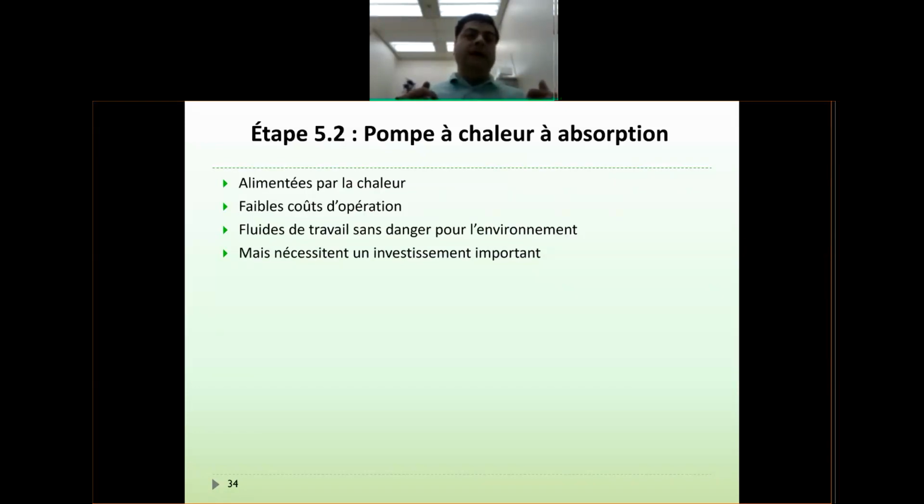So if you remember, when we discussed the six steps of process heat integration, the sixth part was to apply technical analysis. You have to do technical analysis and find out if considering a heat pump in the heat exchanger network is worth it or not. That is really related to the economy of the process. But something else that I want to pay attention to is the working fluid in the heat pump. The working fluid should be environmentally pleasant.